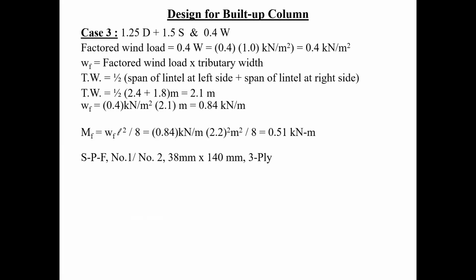In other words, now the only problem is that we're going to get the values for number 1, number 2, but what's the real grade of our wood? Number 3, the stud grade. Okay, so all you're going to do now is take the value of number 1, number 2, and then adjust it for a number 3. Okay, and I'll show you how to do that.